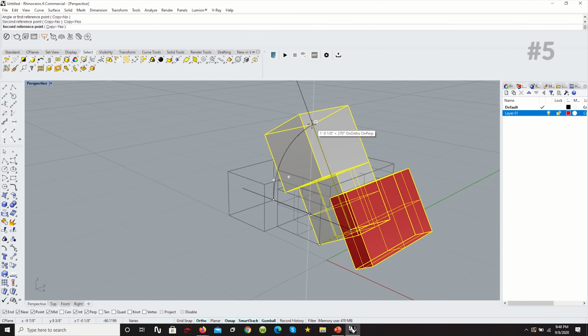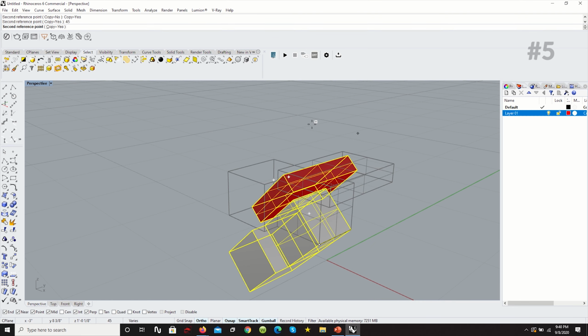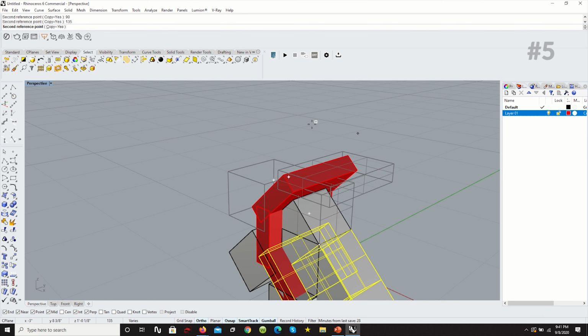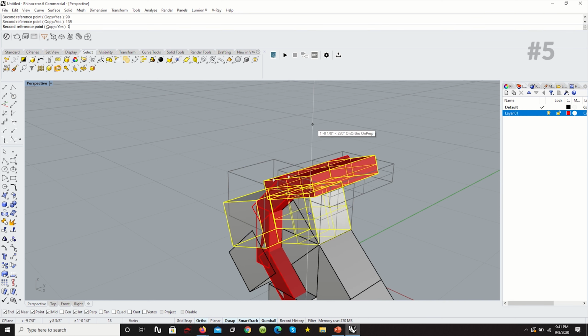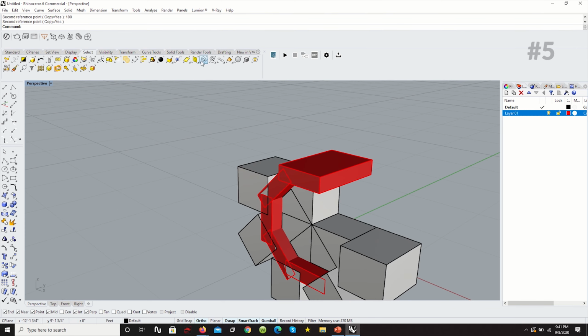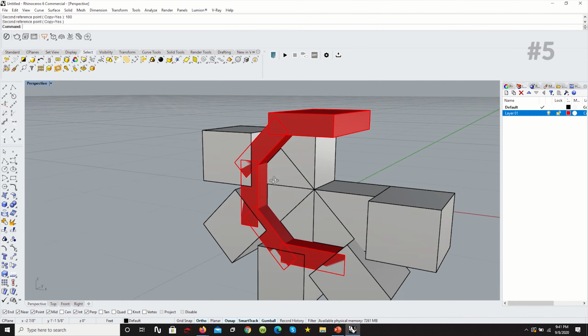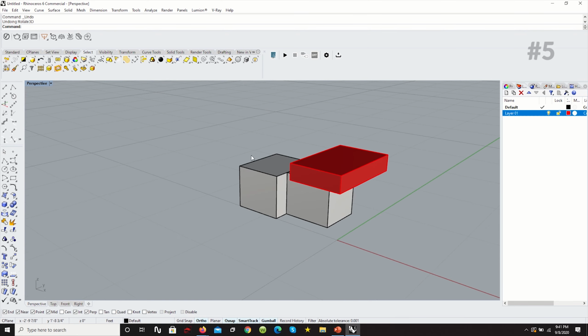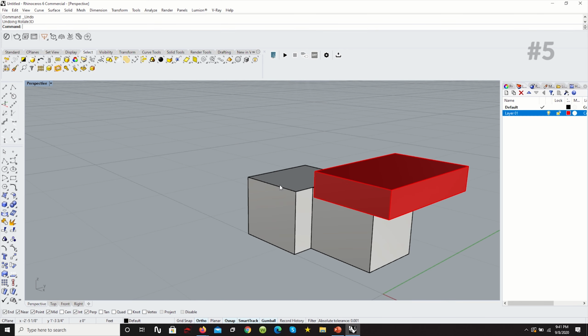So if we go to the command bar, hit copy yes, and put 45 degrees, 90 degrees. Let's do it again, 135 degrees, and again, 180 degrees. You start to get this pattern, and you can create a lot of interesting patterns like that. So let's undo that. But these are some basic transformation tools to get you started with this program and help you do a lot of interesting geometries and offset it and place it in very compelling ways.